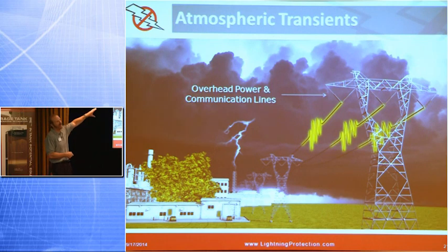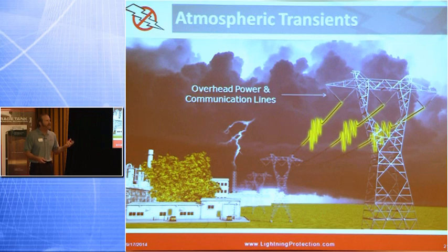Here we're showing you on transmission lines. Probably not a good example. Why? Because transmission lines are running at, what, 230 kV, for example. They're not going to care about it. But if that's a low voltage analog circuit, it's a big deal. Transmission line running at 230 kV or 120 kV, no big deal because it's a kilovolt impulse anyways. But if it's a low voltage line, that induces a low energy transient, that can be a problem. For example, in a refining environment, in a power plant, they use a lot of overhead cable trays. That would be an issue where they could induce a voltage on those overhead cables in that cable tray.